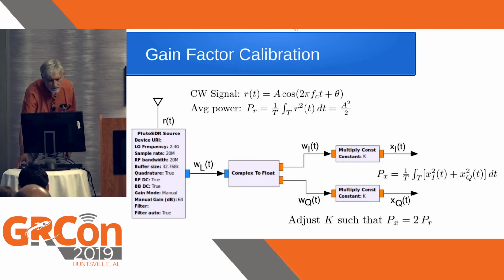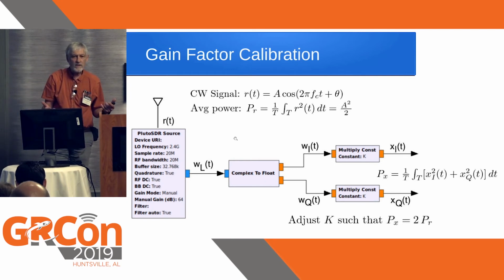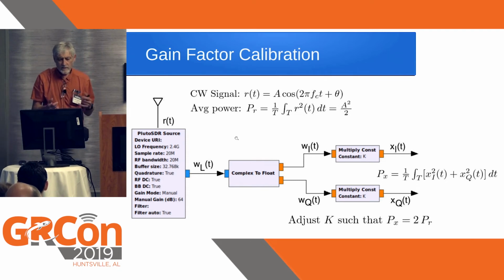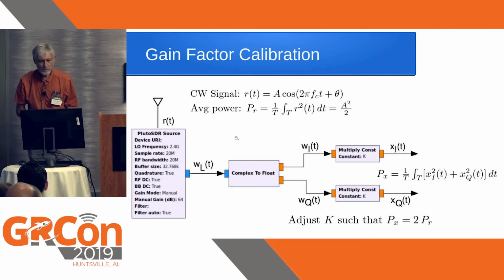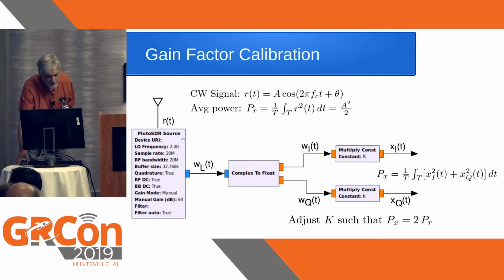So that's the CW signal here, the continuous wave signal that runs at FC. And then you have some frequency FX that's determined by your software-defined radio. So you're actually not going to receive something at an exact frequency. There will be no exact frequency or phase relationship between the transmitted signal and your SDR that's actually receiving it.